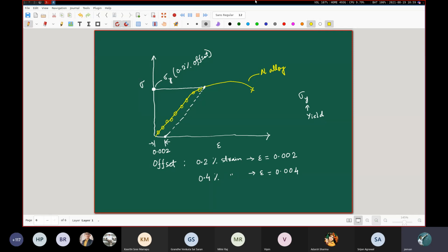So one small doubt, sir. Can we use strain gauges to get a continuous plot and all? You can use strain gauges to obtain the values of strains at a particular point. But here we are not talking about that kind of strain. We are talking about the strain considering the entire gauge length. Gauge length means when you take this kind of a cylinder, you mark out 2 points on it, relative to which all changes in length are calculated. Okay, so this is the gauge length.